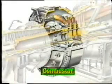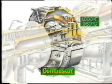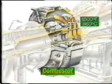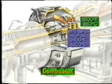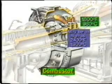As a result of combustion, the temperature of the gas entering the turbine is raised to, say, 1,800 degrees Fahrenheit or 980 degrees Celsius. On large, modern machines, the turbine inlet gas temperature may be as high as 2,400 degrees Fahrenheit, say 1,300 degrees Celsius.